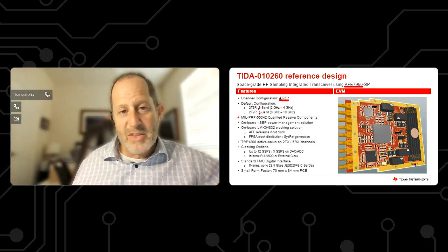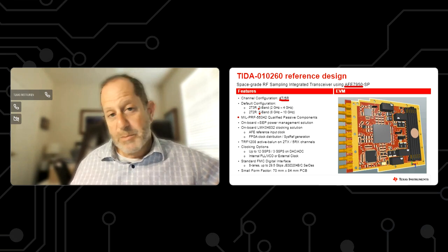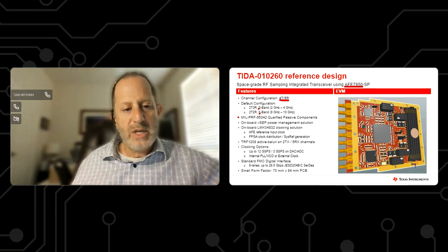There's limitations in capacitor physical size, values, so it certainly makes it challenging for high-speed work where you're trying to get very low capacitor values, and then for bypassing purposes, very high capacitive values. And then certainly the inductors for a lot of the DC switching power inductors, this is a tricky area as well that I found out with this reference design.